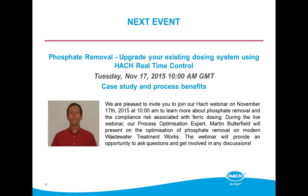Okay. As a follow-up to that one, the same person's asked another question. Would it be sufficient to test the supernatant of activated sludge leaving the ASP to give you an idea of the current ammonia that's actually leaving the plant? Yes, well, that's what actually is measured. So we measure the feed into the activated sludge plant, and we measure the outlet of the activated sludge plant.